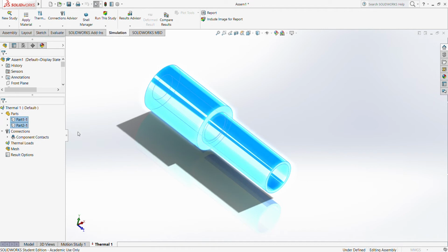Now SolidWorks has a database, and it's defaulting a material of alloy steel, but for some reason it doesn't really recognize it unless you select it. If you tried running this, even though it's telling you it's selecting alloy steel, the analysis would say you didn't select a material. So I'm going to go to aluminum alloys. There's SolidWorks materials and there are DIN materials, and I think it's kind of the same.